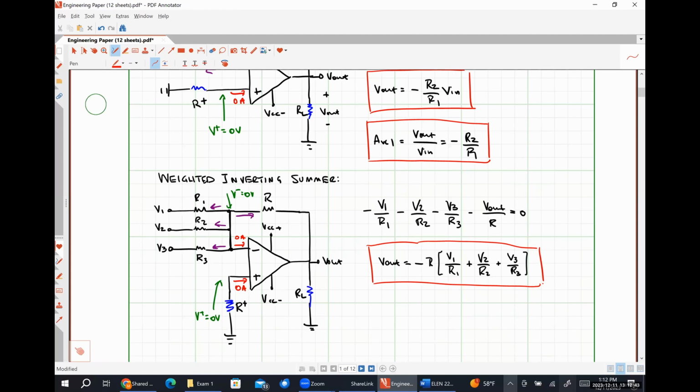So it's not to ensure that no current is flowing through the op amp, because the internal resistance does that. There's a quantity called input bias currents that are due to manufacturing errors in the op amp fabrication process, and this resistor is to try to cancel out some of that. We'll talk about that more when we get into our electronics classes, talking about how more of the internal workings of one of these works. Because from an analysis perspective, this R does nothing, because we're not paying attention to what's happening inside of this thing.